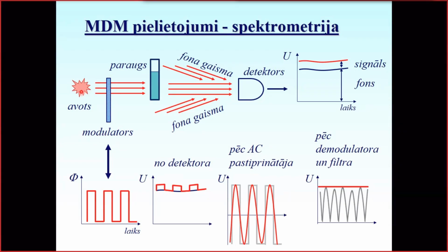We make the light beam falling on the specimen oscillate, to switch it on and off. If it is oscillating, then the detector accepts a signal from the background, which will be steady, more or less. Of course, it will change gradually due to the change of the daylight, the change of the sunshine, and switching the room lights on and off. But on the base of this high and slowly changing background, we will get short pulses related to the signal going from the source.